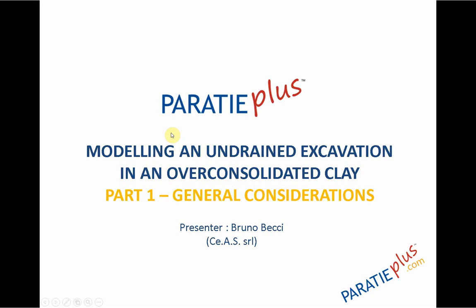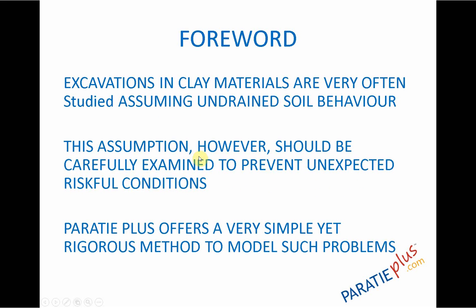In this video, we will give a look to the option provided by Paratie Plus to model excavation into over-consolidated clays in undrained conditions. When you have to design an excavation in a clay material, you normally assume that the soil reacts in undrained condition. We will review this concept very briefly.